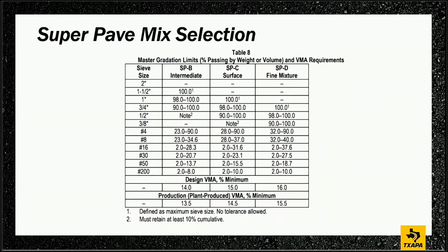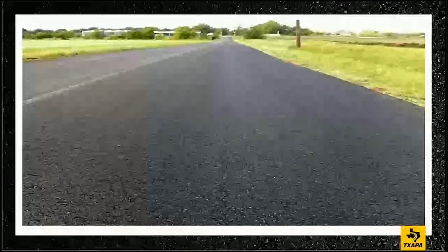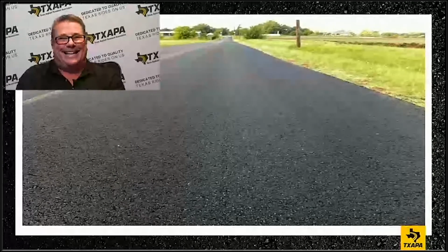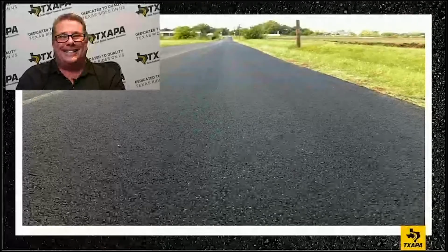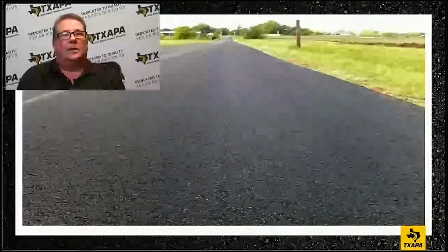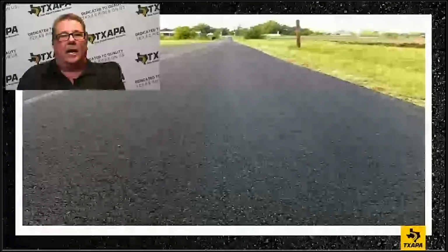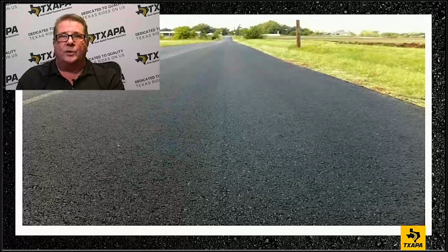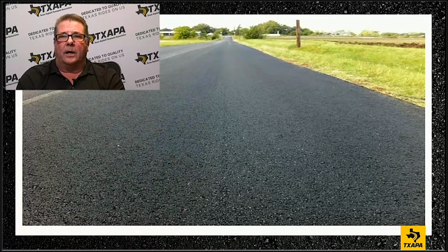Okay. Again, design, engineered. This is Superpave C as in cat. Nice looking asphalt. There it is, C as in cat. That's for Jenna out there in the world. But C as in cat, it's a Type C. It's a 64 minus 22. Again, as you can see, this is a farm to market road. Farm to market road, Superpave C, 64 minus 22.